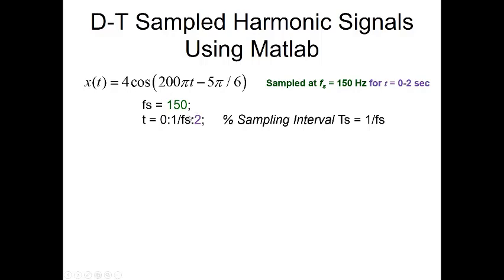And probably the best way to do that is using MATLAB's incrementing array function, where you'd specify the start value, the end value, and what the increment is between values. In this case, we can use a precise increment that's exactly dictated by the sampling rate. The sampling interval is 1 over the sampling rate.